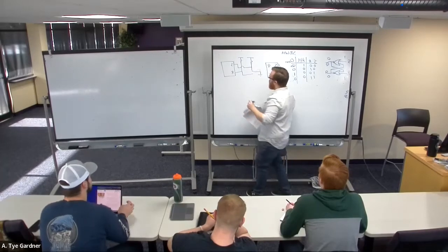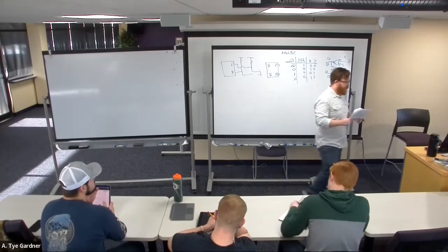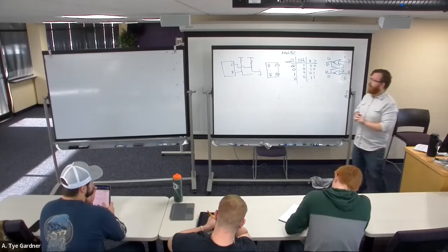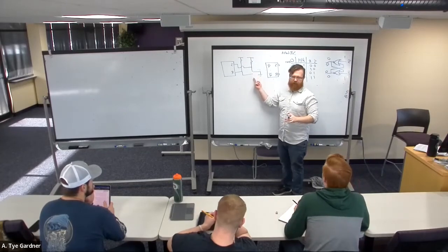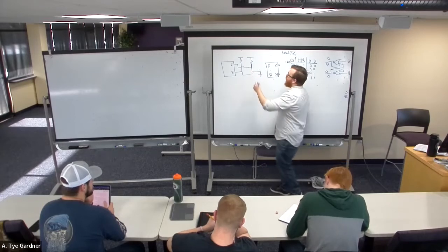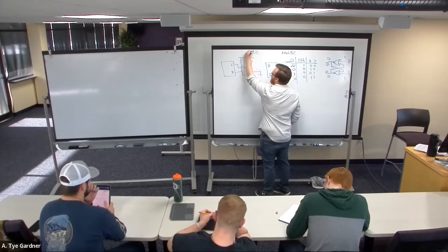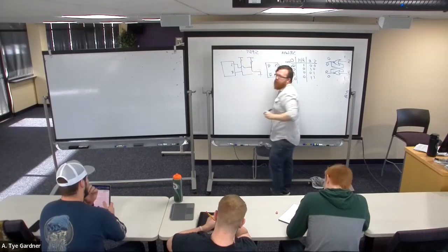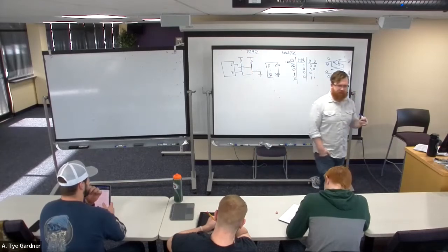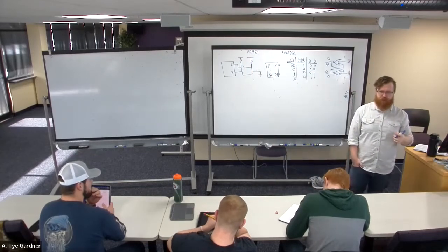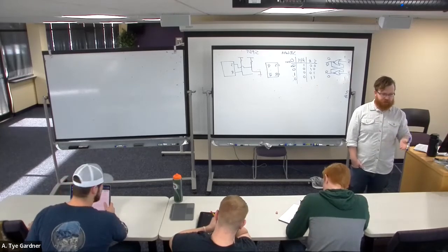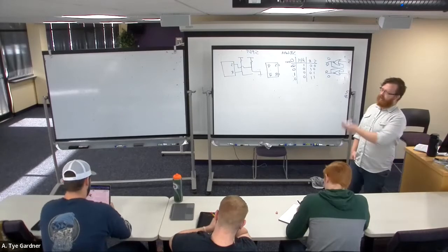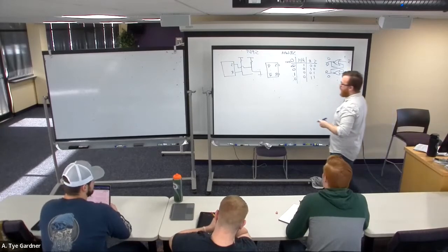Okay, so here I'm going to introduce a new component that you will encounter eventually in your career, which is a switch that is not just on or off, it's in one of two locations. This is called a single pole double throw. Single pole meaning it's one thing that I move, and double throw meaning there's two positions that it can connect to. So the on or off switches are single pole, single throw. They're connected or they're not. Single pole double throw can go to one of two locations.